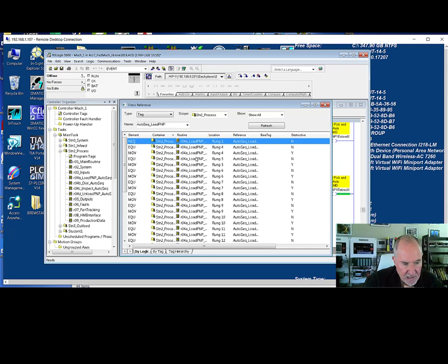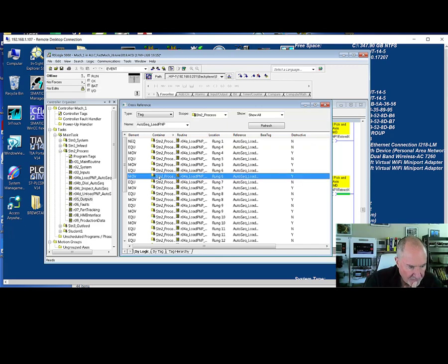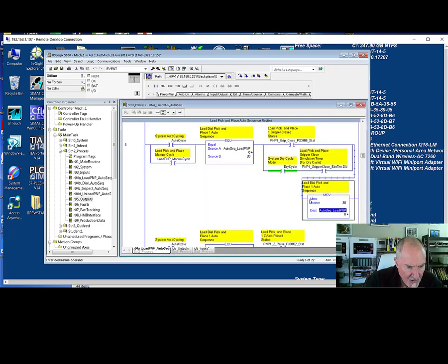And as those of you who followed how sequences work, these are all moving different numbers, right? So you see that the rungs are in order. I've got rung 4, rung 5, rung 6, and they're all in the same routine. So I'm just going to pick one, and I'm going to say, why, for instance, did I not go from step 20 to step 30? And you can look at the logic here and see why I didn't go to that step.